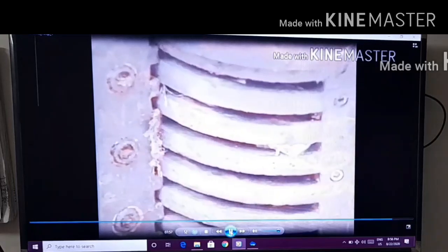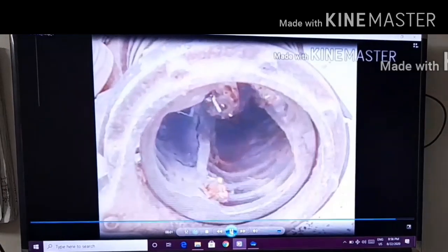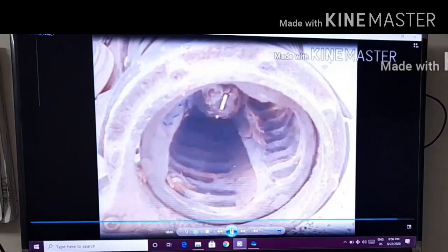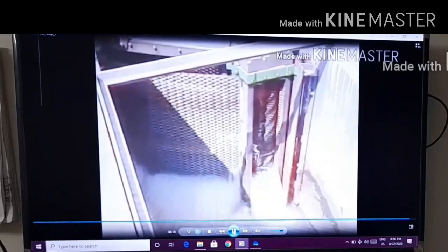Comminutor cutting heads and teeth take quite a pounding and need to be replaced periodically. In most cases, the majority of wear of the comminutor occurs on the lower half of the unit. On some comminutors, it is possible to swap the bottom and the top teeth in order to even out the wear of the teeth. There are many types of comminutors and similar devices on the market today. As with all mechanical equipment, extreme care should be used when working on or near this piece of equipment, as it is capable of chewing off body parts with ease.